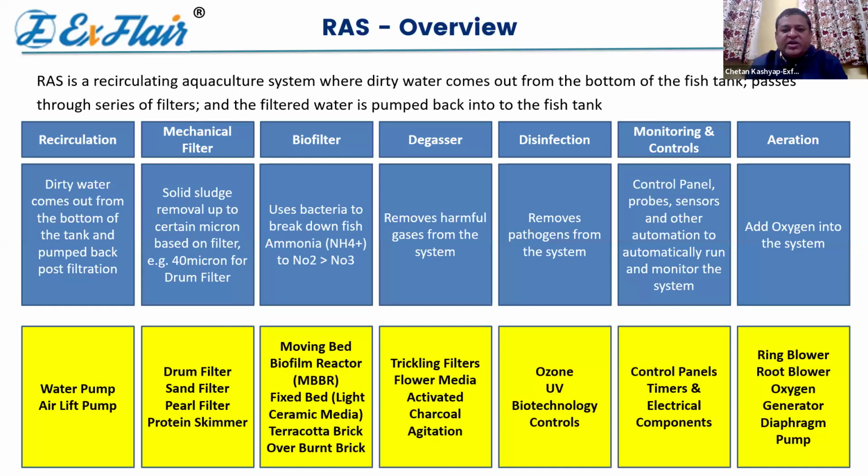Now, the other thing is that during the process, once the excreta and urine start getting broken down into various particles, there are various gases that get produced. Some are very deadly, like small traces of it can kill your whole culture. Like H2S gas is a very deadly gas. So we also have to remove those gases.